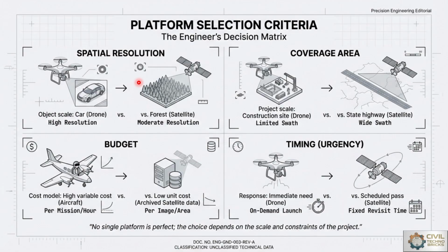Selection of a remote sensing platform depends on project area, resolution requirement, revisit frequency and the budget allocated. Ground platforms provide detailed location information, whereas satellites are more suitable for regional assessment or analysis. Unmanned aerial vehicles and airborne platforms bridge the gap between field surveys and satellite observations, and proper platform selection enhances the efficiency and reliability of civil engineering investigations.